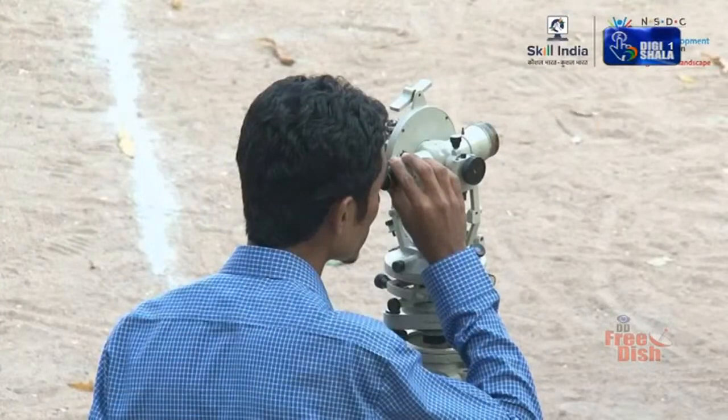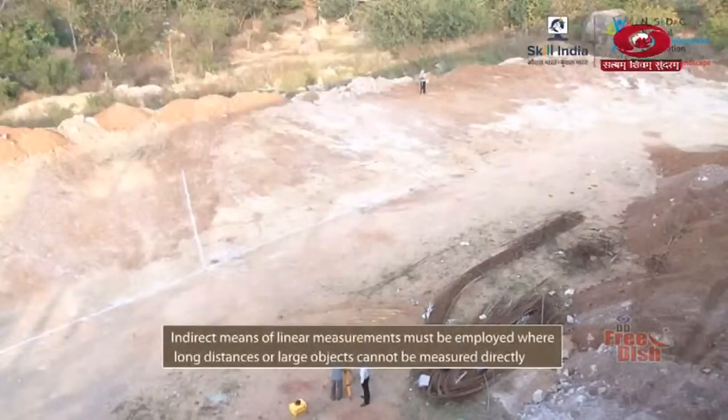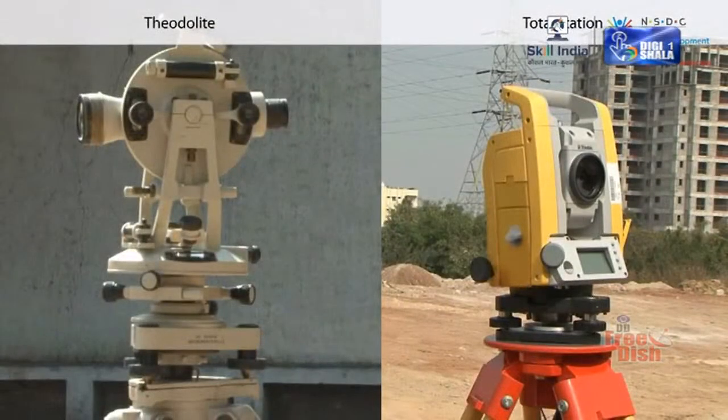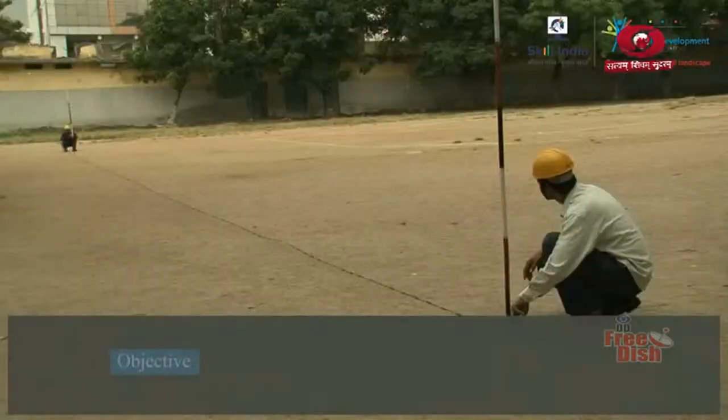In this module, you have learnt about the indirect means of linear measurement. Indirect means of taking linear measurements must be employed if the survey has to cover many long distances or if the ground features or objects on the site are too large to be measured directly. The two instruments used for taking indirect linear measurements are theodolite and total station. The theodolite is an optical instrument that measures angles with the help of which height of objects can be calculated.